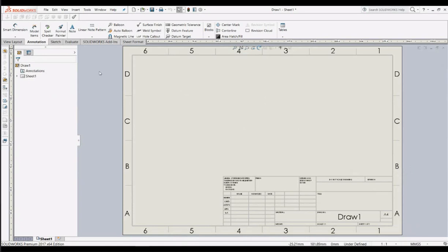In order to do that, as I showed you before, we are going to take our cursor to the bottom right corner of the document. At the bottom right corner of the document, you can see something like this. It shows you the IPS, right? I think the IPS is the default, but you have to change it. Put your cursor on the IPS and left click it, and the options will appear. In the options, you have to click the millimeter, gram, second option. So this is our standard unit now.